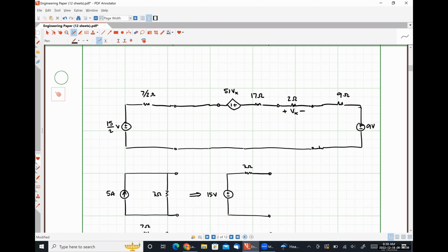What Thevenin's theorem and Norton's theorem allow us to do is effectively replace any circuit with a practical voltage source representation or a practical current source representation, but it doesn't rely on just using source transformations to get there. So in some cases, it can be faster to just find a Thevenin equivalent circuit using those techniques than it would be to do multiple source transformations back and forth to make it break down into a practical voltage source or practical current source representation.